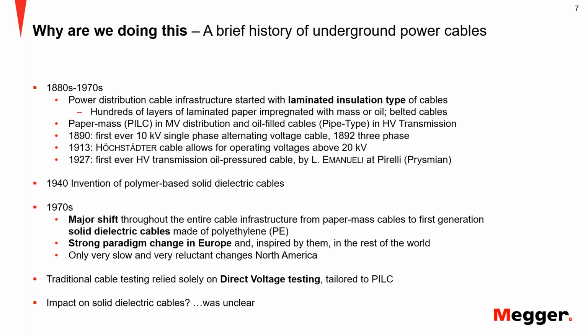And then in the 1970s, a big shift happened. So people moved away from paper cables to solid dielectric cables. And to put it politely, there was a big learning curve associated with this, because the first few generations of PE, of polyethylene cables, were terrible for various reasons. The curing process was an issue initially, and other things.